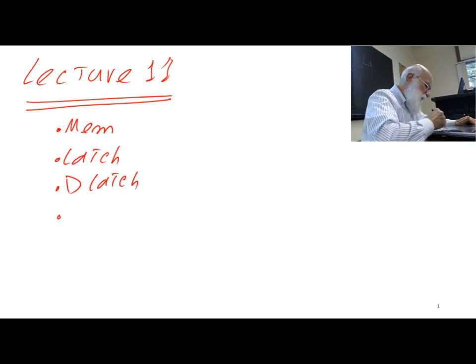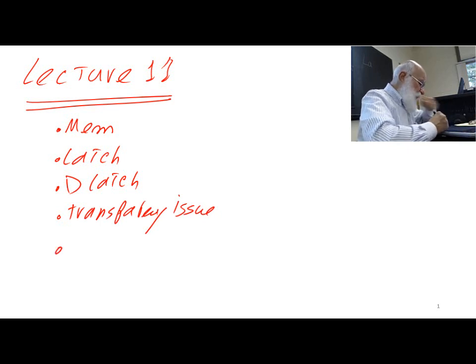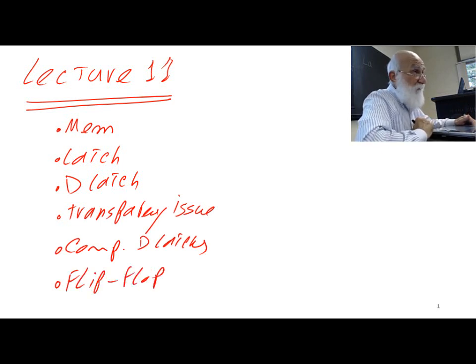It didn't work because of the transparency issue. We resolved that by using complementary D-latches, and then we came up with the flip-flop. That's what we have now.